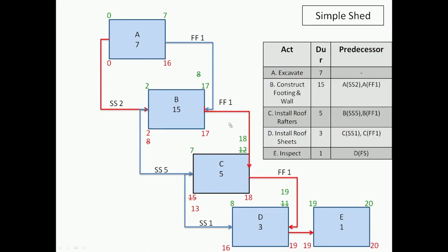So as we come down here, that is between A and B. Similarly, you can see that for activity C, the start of C is not critical, but the end of C is critical. So while the start of B is critical, I have flexibility with the start of C, but I have to end it on 18. This is somewhat realistic, as a subcontractor of C might want this kind of information, rather than saying my whole of C is constrained within a particular range or things like that.